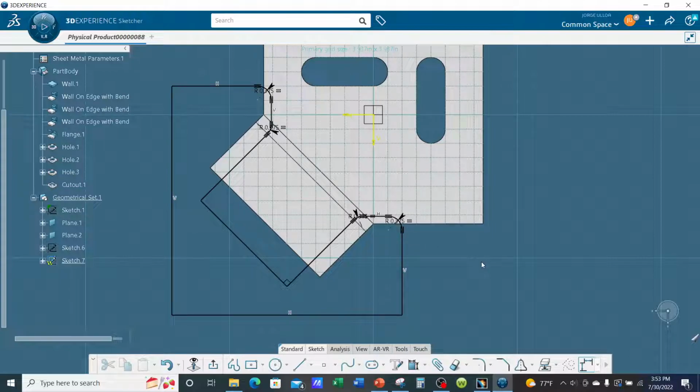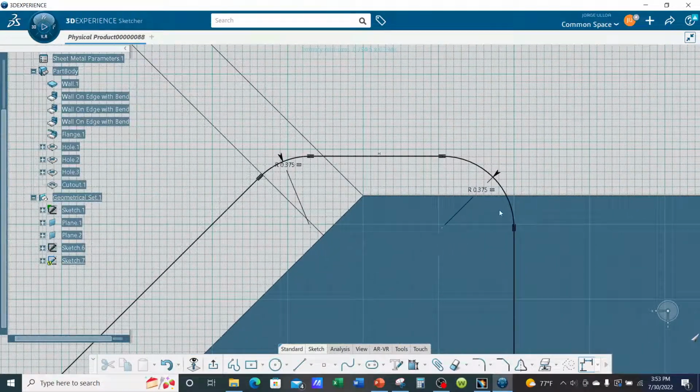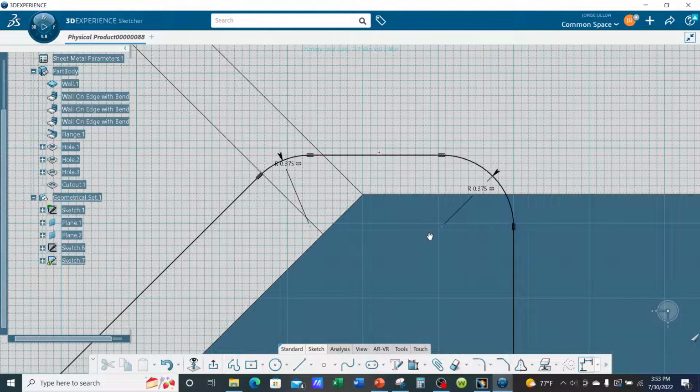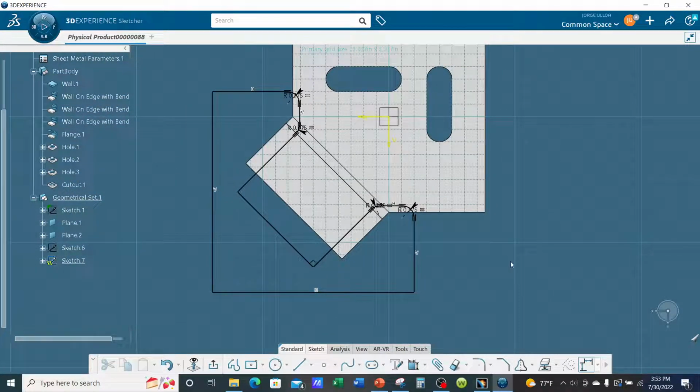As you can see, which you can always delete, by the way, if you wanted to. If you wanted to make a separate radius dimension for one of them, break from the others, you can always remove the equal constraint. Okay, for time I'm not going to constrain the sketch completely, so I'm going to go ahead and exit now.